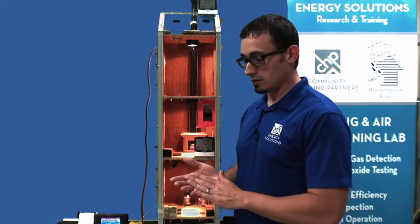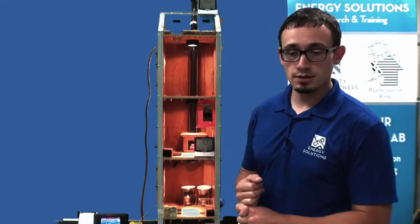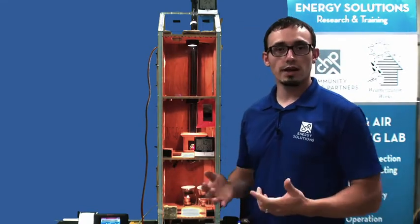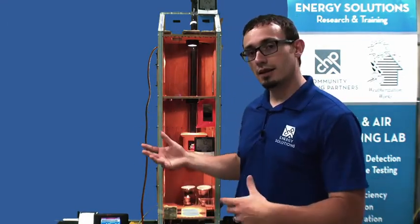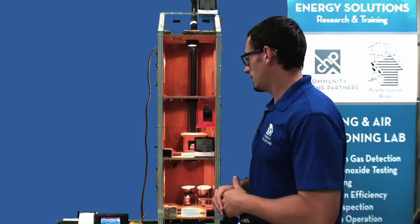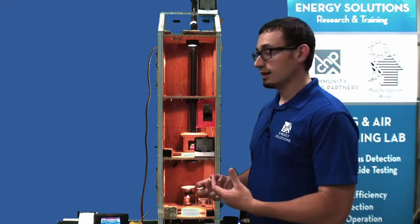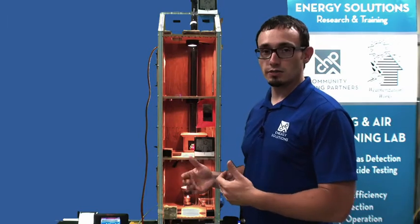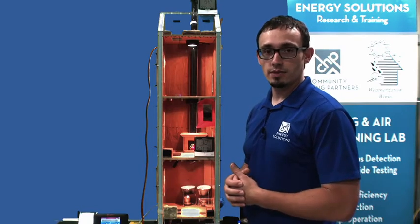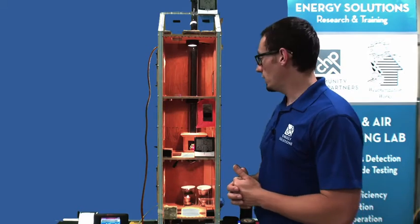And those conditions are, I have to have some sort of pressure difference, and I have to have some sort of hole. Got to have a pathway in a pressure boundary in order to have that. So you guys saw the air movement via stack effect, via that convective loss, but I just want to make sure that was clear. You have to have some sort of pathway to or through that space, and the pressure difference across that pressure boundary to actually have any sort of airflow through that opening.